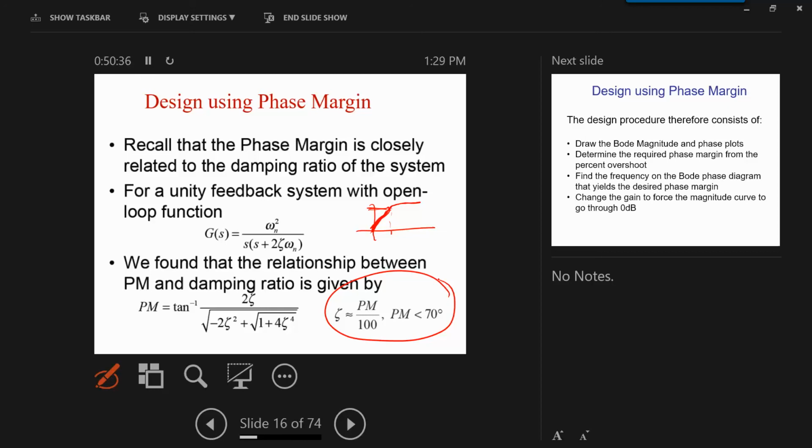And also you have to understand that no matter what, this angle can be only what? The phase angle for a second order system goes to minus 180. So no matter what damping you have, the phase angle goes to minus 180. In the middle frequencies, the curve is very nice, so it can be approximated by a line. And when you get the damping ratio very high, then it becomes not linear.